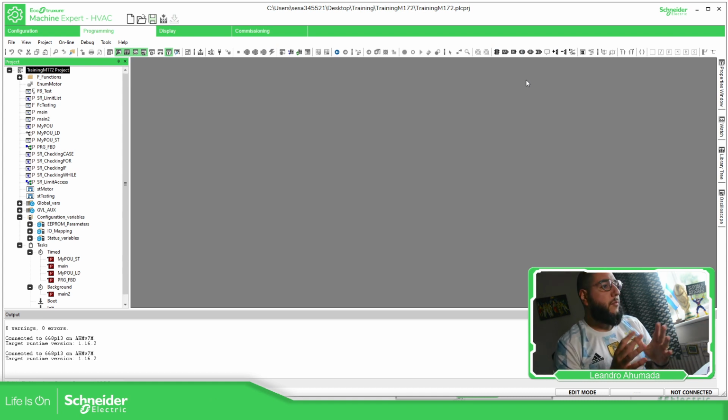So that is something important. Once we connect the USB into the PLC, we should be able to see a COM port. That's the one that we use in order to connect in our software. If you don't see that, probably the gateways weren't installed properly, so reinstalling will be good. You can reinstall the software, and it's going to be very fast.